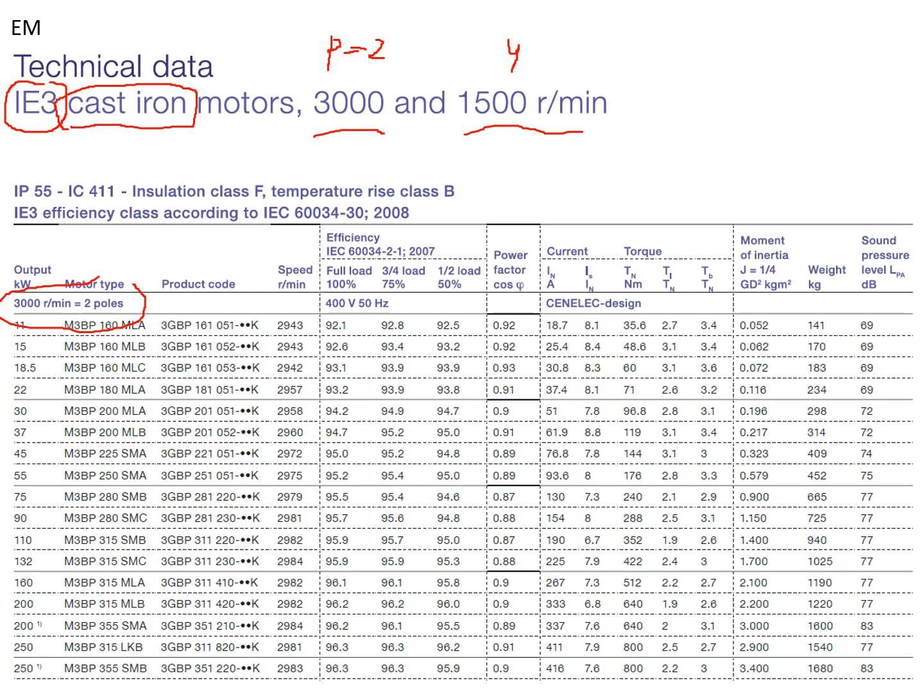Basically, catalogs are quite well organized. At least I like ABB catalogs very much, but other catalogs are quite similar in structure. What you will find here is powers on the left-hand side, and speeds. You see all the speed numbers here are slightly below 3000, and this is because of the slip. And we are talking about induction motors all the time. I probably forgot to mention or stress it in part number 1 of this lecture, I was talking about induction motors first of all. So we have slip, and the speed is a little bit lower here.